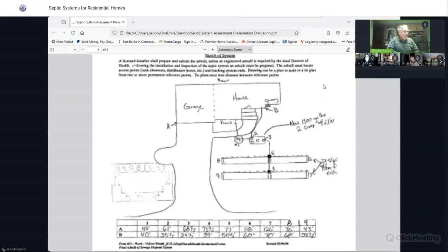And so that was one of the problems that I was hired by the homeowner to look at, and we found out there was no line. The system wasn't installed properly, obviously. I mean, that causes big problems. And that's one of the reasons that the pump chamber in that picture I showed you has the black marks. That was too much effluent going down. It wasn't nearly sized enough. It was only sized for that bathroom downstairs, not for the whole house.